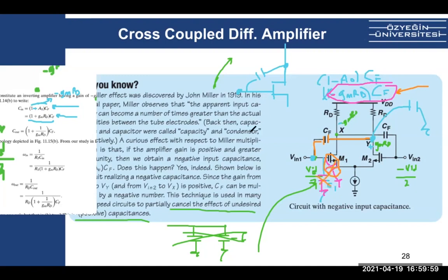And what we do is, if this is the input pole, basically we are canceling this pole. That's amazing, right? And this is used in high-speed circuits because why is it high speed? Because we can increase the bandwidth. If we remove this, now the second bandwidth is at this point, the pole, right? So we significantly boosted the circuits, okay? That's why it is used in high-speed circuits.